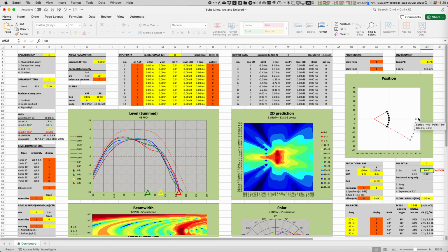And if you remember from the other video, 67% from the on-axis to the outside, that intersects the last one, is where you will cross more than 6 decibels of attenuation. That is basically here, microphone 6 and microphone 7. So microphones 6 and 7 are showing more than 6 decibels. So in other words, the usable area in this case is not 60 degrees, but 2/3 of 60 degrees, that in reality is 40 degrees. This is the usable area if you don't want to cross the -6 decibels.